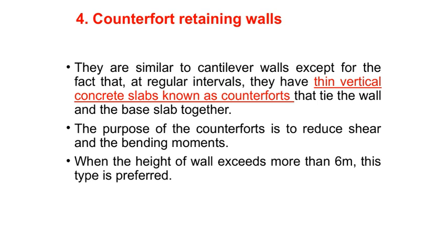You'll typically see this type of wall used when the height exceeds about 6 meters. In such cases, the added reinforcement provided by the counterforts is really beneficial, making the wall more stable and durable for taller retaining structures. So, in the overall context of retaining wall design, counterforts are an important solution when dealing with higher loads and greater heights, ensuring safety and longevity.